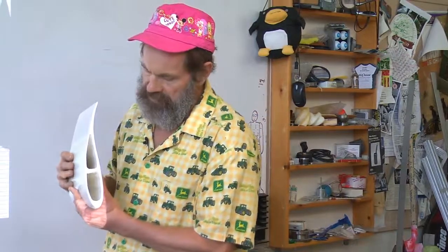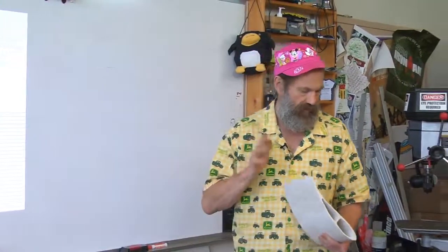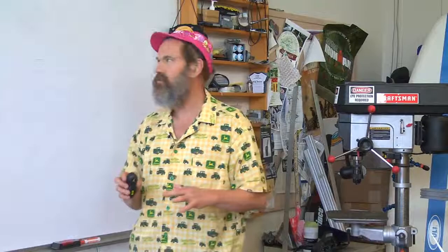This is the section from a Berge wind turbine blade. Notice how, and this is a pultruded fiberglass, this aerodynamic section, this airfoil, was actually pulled out, or pultruded, as one piece, very, very torsionally stiff, bending stiff, but made of simple plate sections. So remember the power of the neutral axis theorem in using extrusions and extrusion-type processes to achieve very, very high stiffness and strength from what otherwise may be thought of as soft plates.